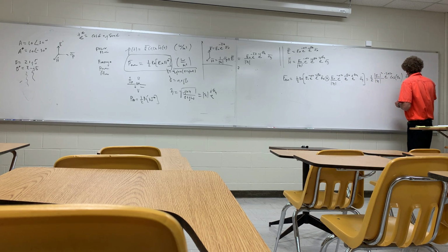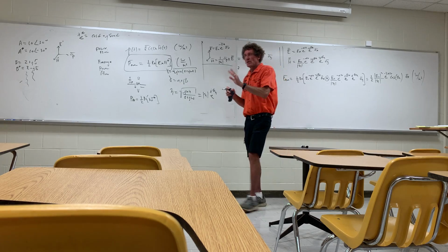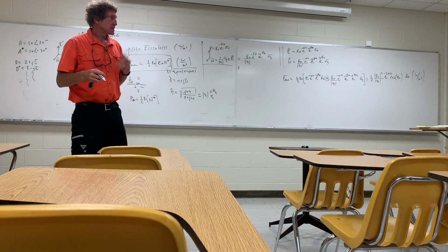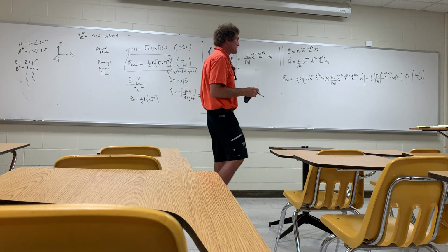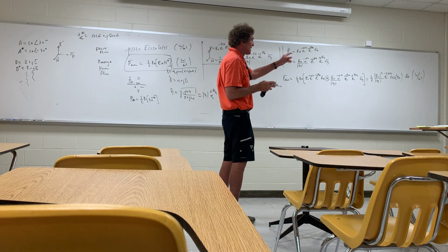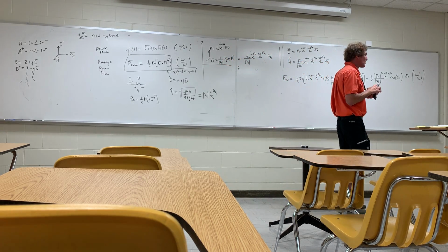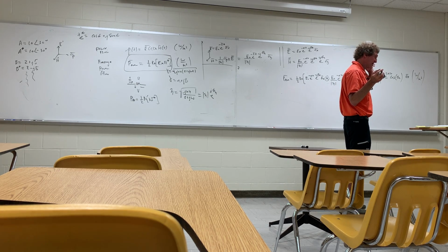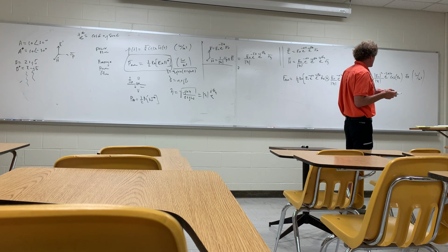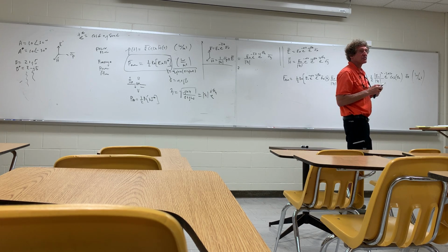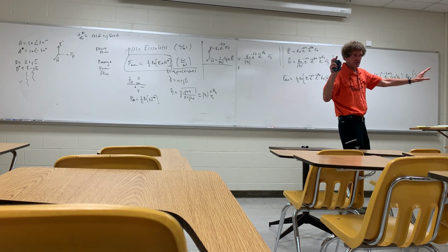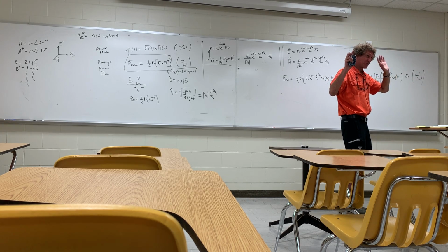And this is important to understand. This is watts per meter squared. So this is power flow generally for a plane wave, assuming it's propagating in one direction. In this case, we're assuming the E field's in the X direction and the H field's in the Y direction, but it doesn't matter. That power flow applies to any E field propagating in one direction, in either Z, X, or Y. You could replace Z there with X or Y if it's propagating in the other two. And it's also assuming a plane wave, that we're a long way from the source, so there's not that 1 over R fall. It's a plane wave.